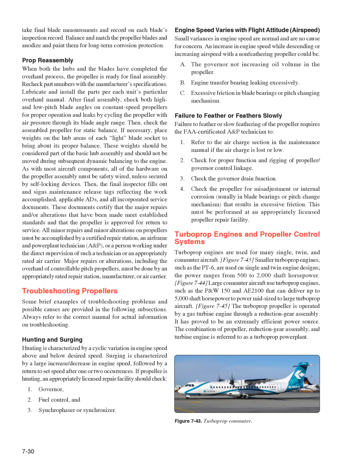Then, the final inspector fills out and signs maintenance release tags reflecting the work accomplished, applicable ADs, and all incorporated service documents. These documents certify that the major repairs and/or alterations that have been made meet established standards and that the propeller is approved for return to service.